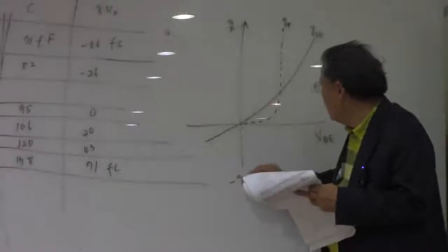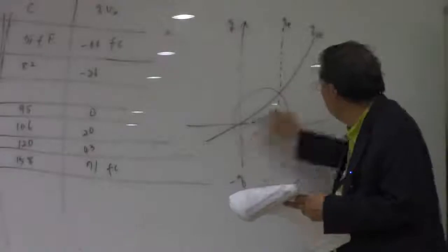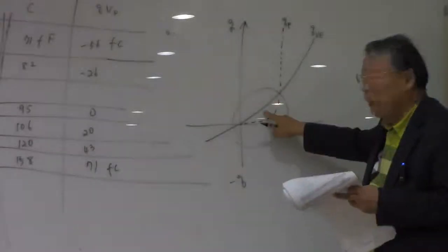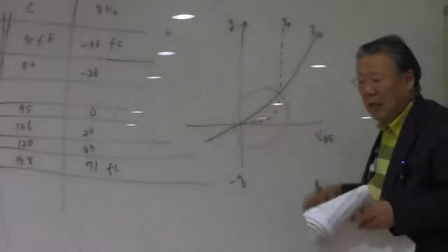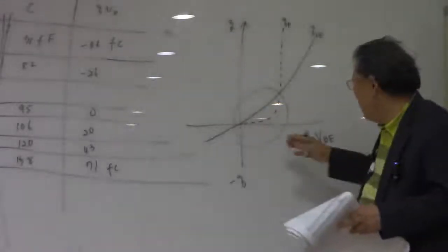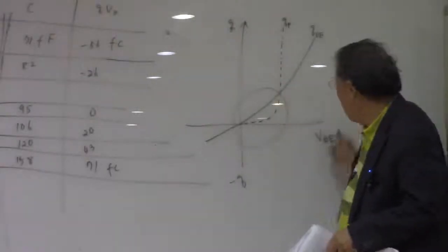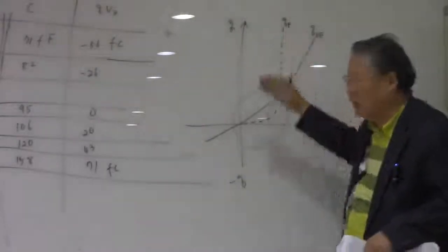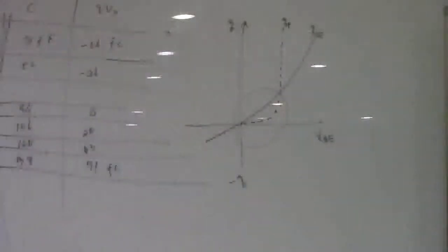Which means at low voltages, space charge is going to be dominant, but at high voltages the injected charge catches up very rapidly, exponentially, so that at high voltages the injected minority carrier charges will dominate the bipolar functions.